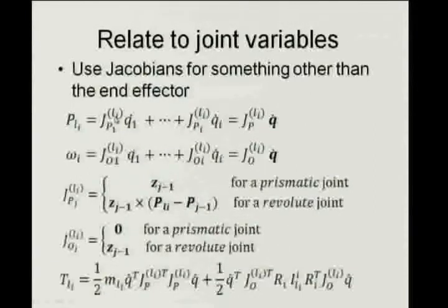In this case we have split into two parts, the component along the axis, the angular velocity component, and the velocity component. So these are the three vectors which have been split up, and this is the definition of it. Then you can write the kinetic energy of a link in terms of that: two components, half mv square term, half I omega square term.